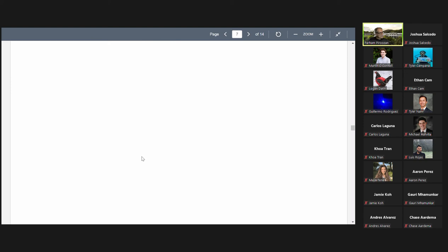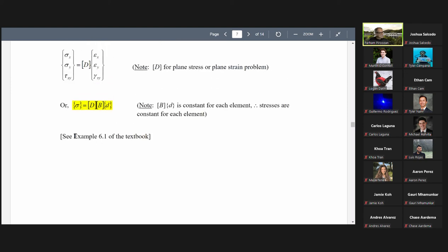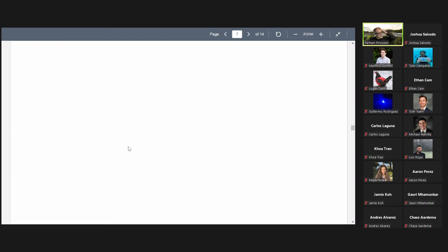So here, let's look at this example problem quickly and see how we can find the stress, assuming we know the displacements, which Nastran's job is supposed to find for us. We will see how, because to find those, we need the element stiffness matrix. Suppose we know them now. Let's apply this formula and find the stress in this problem.